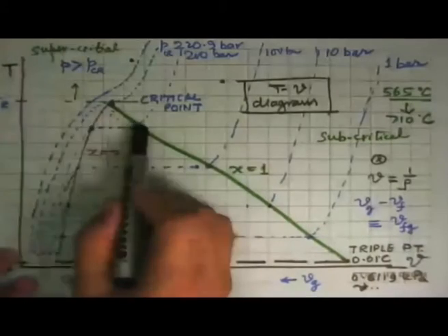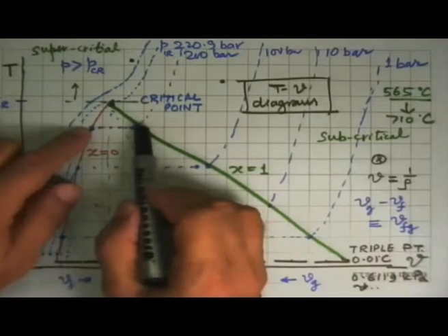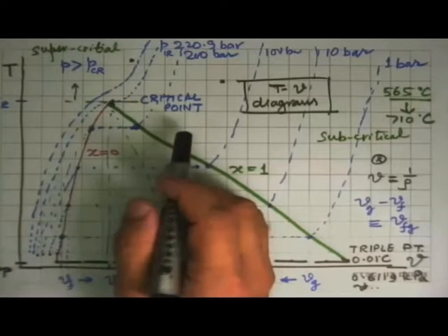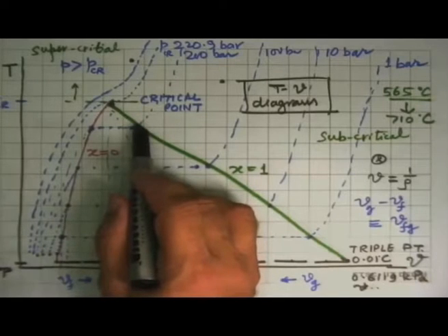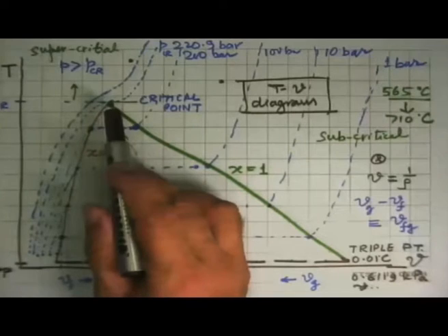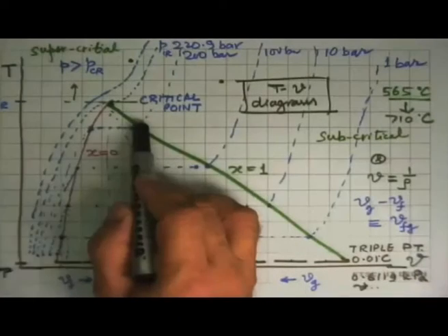So you saw here, below the critical pressure at any point, there was a distinct thing which is called a liquid, where the intermolecular spacing was something. It became a vapor where the intermolecular spacing suddenly increased. This does not happen at the critical point because you have increased the pressure so much that this inhomogeneity that we saw has disappeared.